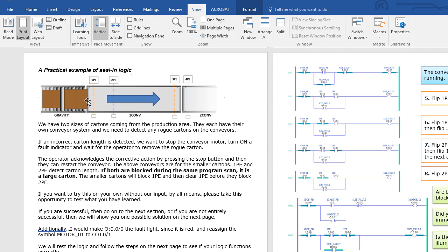the conveyor. So when it blocks this photo eye, you could stop the conveyor if that's what you wanted. Or when it hits this one, which means that it's all the way onto the conveyor, and this carton trailing behind is now up against the edge of the conveyor, you could stop the conveyor then. Or when the carton travels all the way and interrupts 3 PE optical path, you could stop the conveyor then.